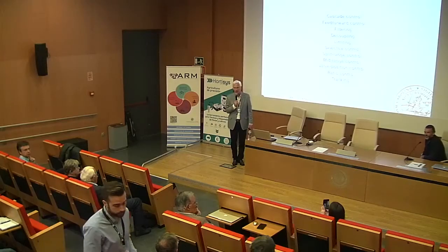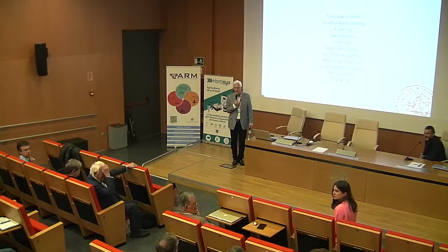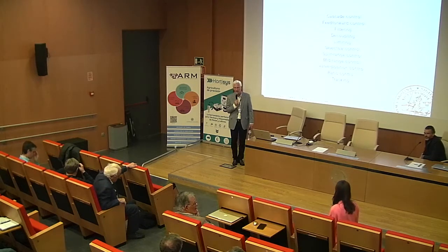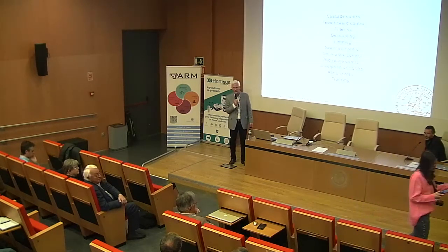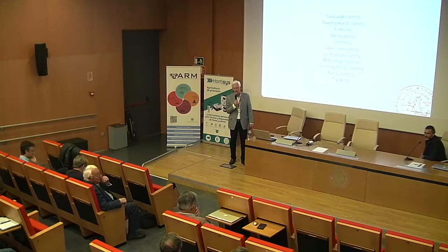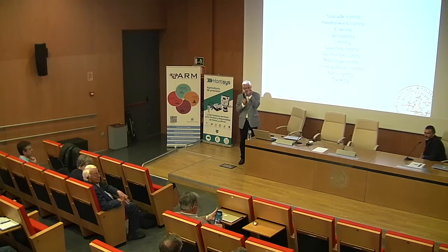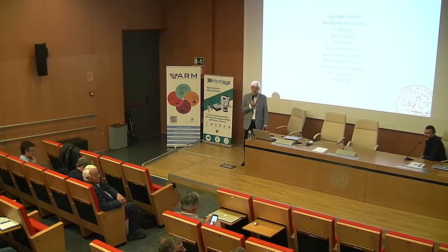Well, I would like to talk about industry. Most of the processes are multivariable. So if you want to have the tires in good shape, as you say, you have to solve that coupling at that level. I understand that feed forward can help, that ratio is a kind of multivariable, but I think that the coupling that is in that list is very important, because if the regulatory level is not well, then you have to rely on the advanced control, maybe on MPC, but you cannot solve that decoupling. My question is, are you or the research group working on decoupling?